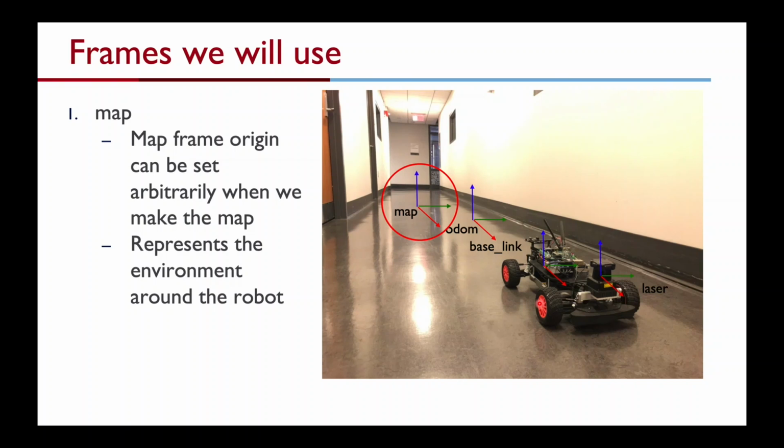In the simulator, you will have a map frame, and then the pose of your car will be reported in some coordinate system, and the theta in terms of the orientation, always with respect to the origin of that map. So the map frame is quite intuitive, and this can be placed arbitrarily, but once it is placed, it typically never moves during the entire robotic experiment or data collection or whatever you want the robot to do.